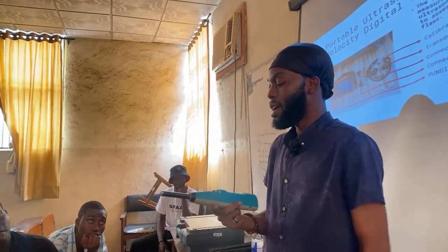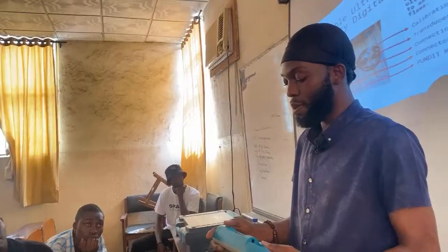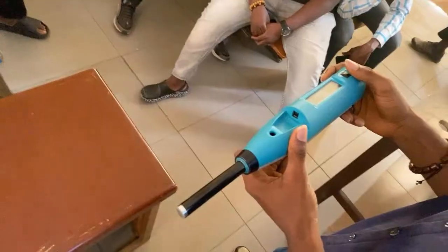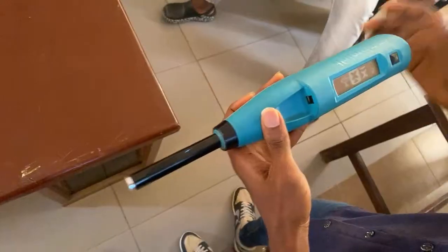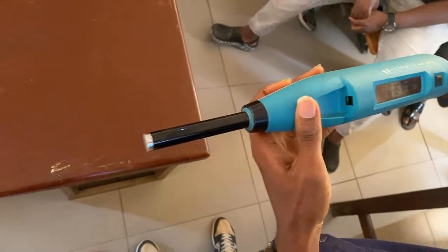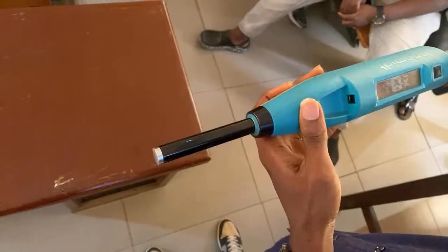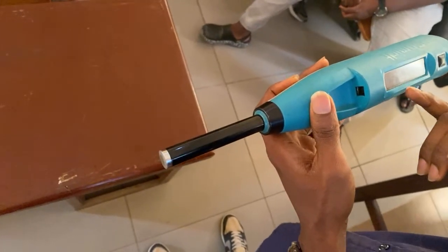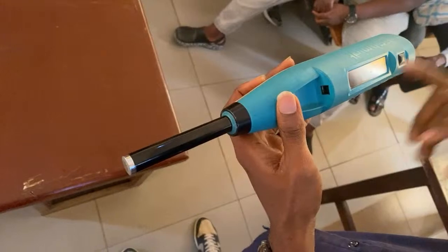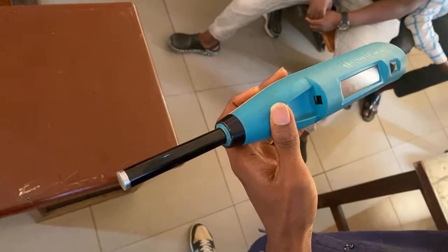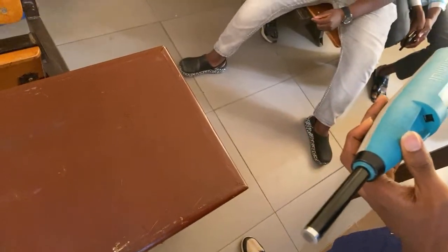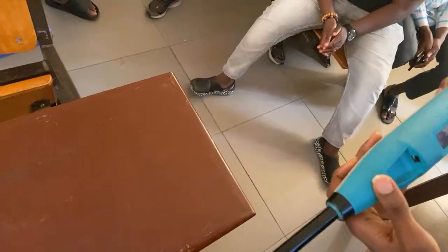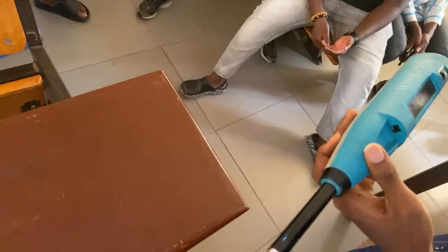You understand? There is a particular place on the Schmidt hammer where you select how you get your rebound number and your compressive strength. Either you use the American standard method or you use the median. When you are using 9 shots, it will definitely be the fifth shot that I use as the rebound number and compressive strength. But we will use the mean. So this is the mean now.